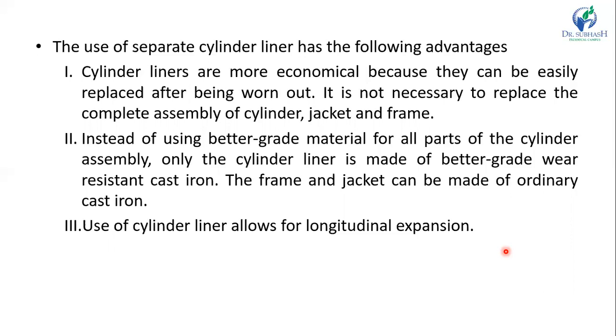Instead of using better grade material for all parts of the cylinder assembly, only the cylinder liner is made of better grade wear resistant cast iron, so the frame and jacket can be made of ordinary cast iron. And the cylinder liner allows for longitudinal expansion.